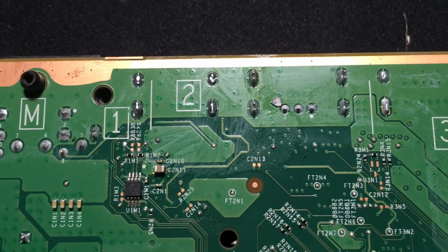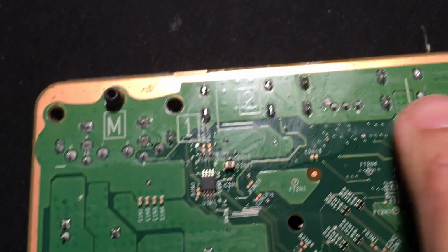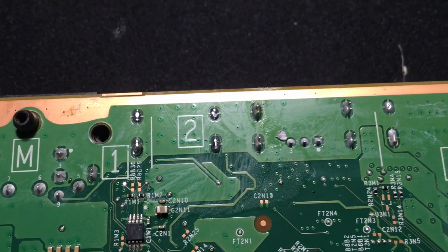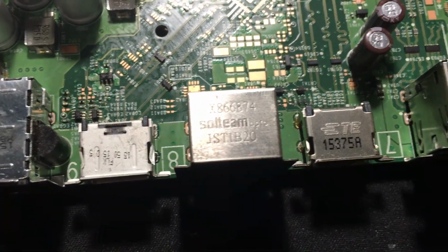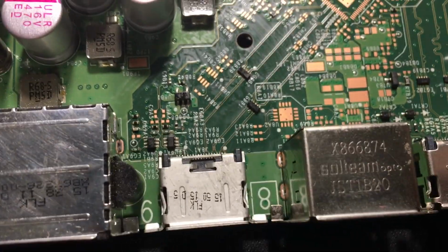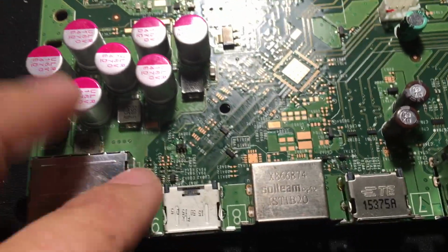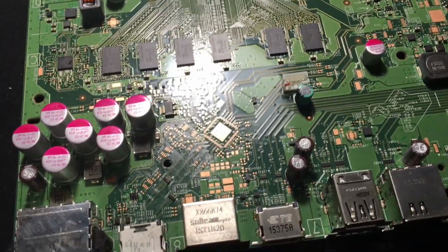On the bottom side here, we can see our newly soldered in port versus the original. This is the HDMI in, and this is the HDMI out, as far as I know. I never used the HDMI in, but I assume it was okay, but it doesn't matter. It isn't the focus of this. But here you can see the top. Clearly this is the replacement port, marked by the FLK, and this is the original port. So everything's soldered down correctly, and I just need to apply some thermal paste on the CPU, get this whole thing put back together again, and try out our HDMI port and see how it goes.